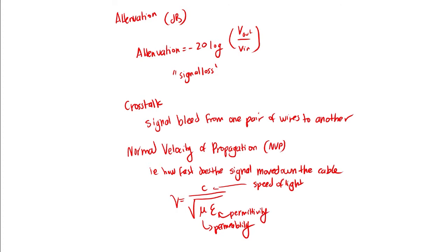So in any cable, for example, we're measuring V as a percent of the speed of light. And under ideal conditions, could say it's 1, but typically on a data cable, it's between 60% and 70%.